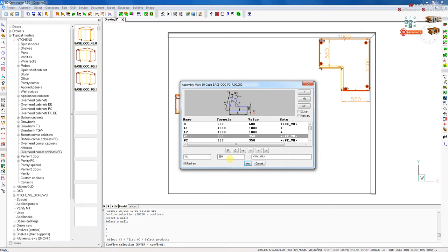We never have corners in our building at a straight 90 degrees, so we can fit our corner cabinet on the wall. We recommend having our corner cabinet sitting off the wall by a packer size, let's say 16 or 20 mil, depending on what you're using. If the line of our cabinets is 350 mil, we need to deduct the packer size. I'll explain why I'm doing this. And we will click OK.